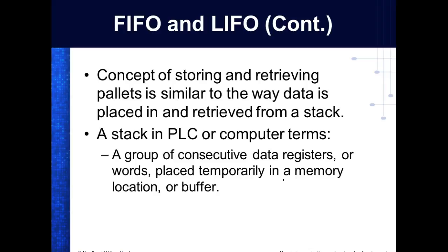So if you need to get the fifth data off the stack, you can use one of your direct addresses and specify the fifth address from the top of the stack. The stack is addressable by any address. What if you don't address it? Then you're going to use a push or a pull instruction. What's nice is that if you use a pull instruction, it automatically pulls stuff off the stack, and once you pull off this one, it goes to the next one and sits there waiting on you to pull.